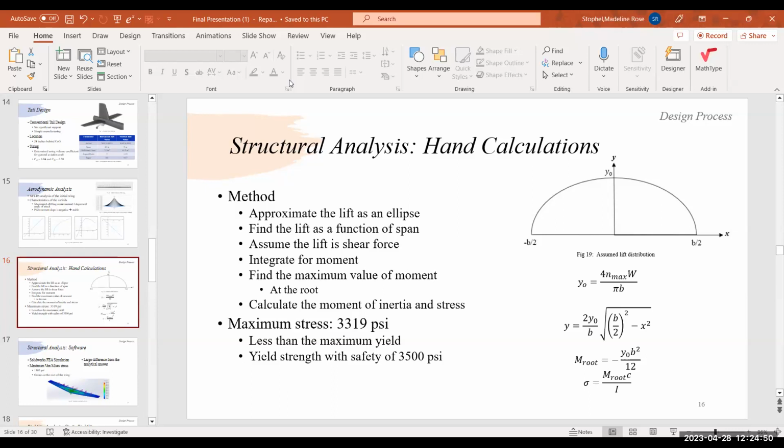Yeah, so one thing you could have done just to help with the stress relief on the actual PLA itself, you could just put tape across the span of the wing, and that would help a lot with the layers being unloaded.